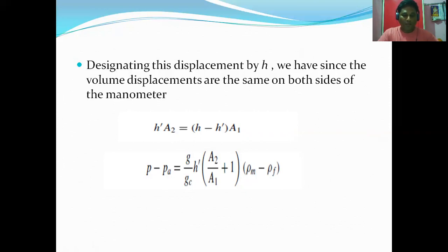A manometer may be oriented in an inclined position to lengthen the scale and improve readability, or special optical sight glasses and vernier scales may be employed to provide more accurate location and indication of the manometer fluid height than could be obtained with the naked eye.